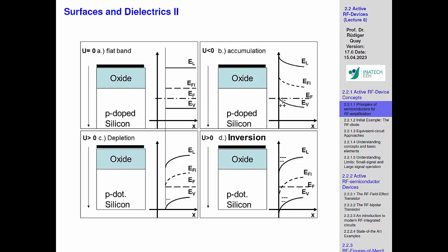What can typically happen is that if there's a bad interface, for example, a fixed charge which resides at this interface because it's of bad quality, then this bending will not work. We call that Fermi level pinning, so that all the bands are pinned just at the interface, and no matter whether you put a voltage or a change at the metal, the field effect really doesn't work. Yeah, so you cannot really bend them down. So this is the exception you have to watch for. And so on a clean surface you can actually bend it down.